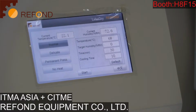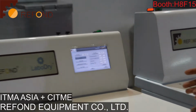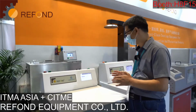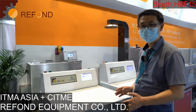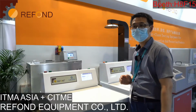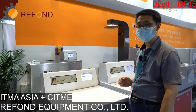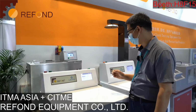So you will ask, what's the function of the humidity? Why do you monitor the humidity in the exhausted pipeline? As you know, if you set a fixed drying time for a certain fabric, you don't know whether the fabric has been less dry or over dry. So if you can set the humidity in the exhaust pipeline, you can monitor the humidity online or at any time.